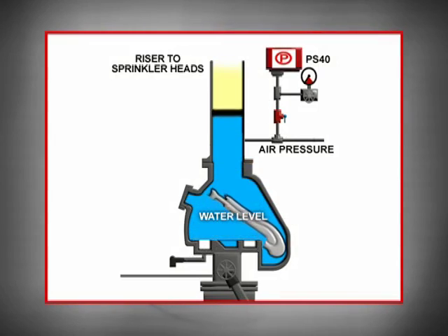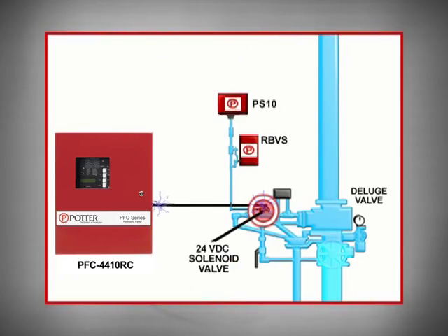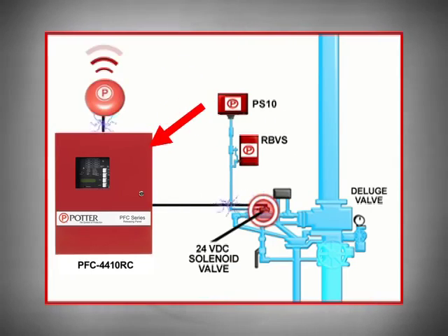The water flows into both the sprinkler piping and the alarm line of the valve. When the pressure in the alarm line reaches 6 psi, the pressure type water flow switch trips and the releasing control panel rings the water flow bell.